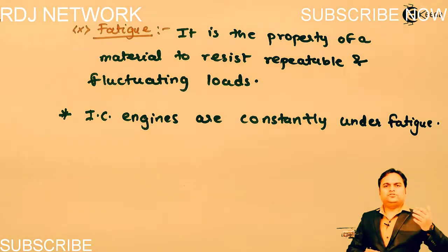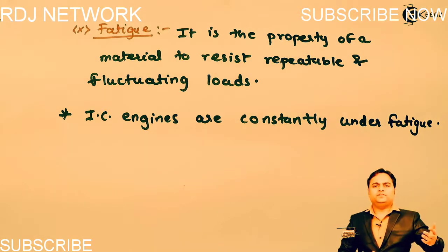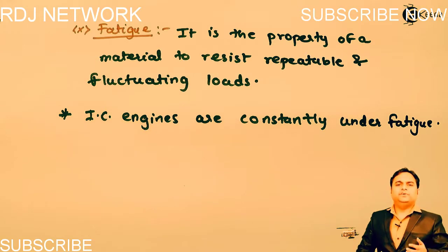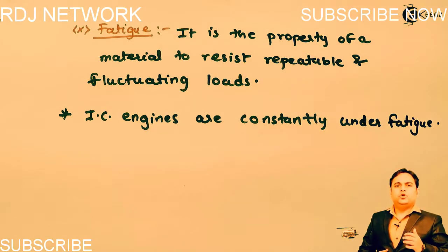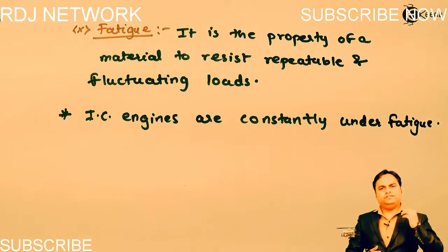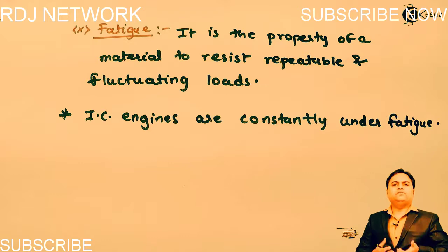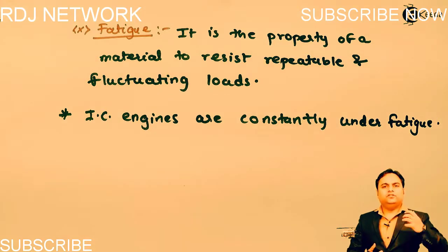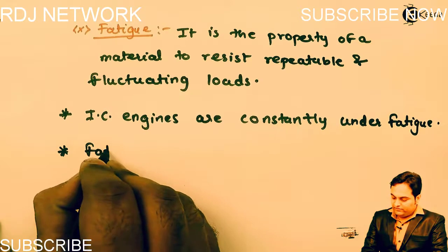Temperature at first, during the suction stroke the temperature is less, during compression it increases, during the power stroke the temperature is highest, and during the exhaust the temperature again decreases. So when it is subjected to continuous variation in load and temperature, that results in fatigue, and because of that the failure which takes place, it is called as fatigue failure.